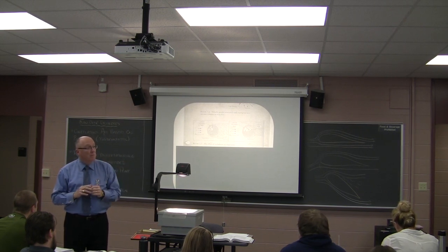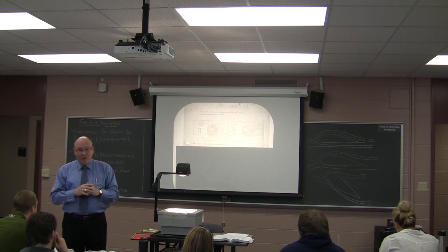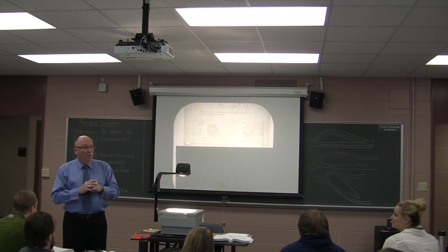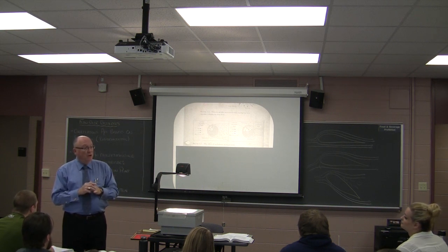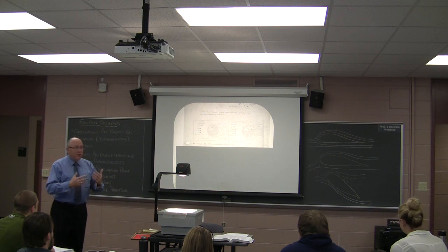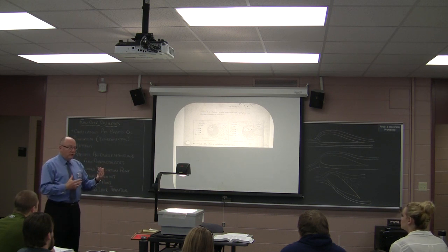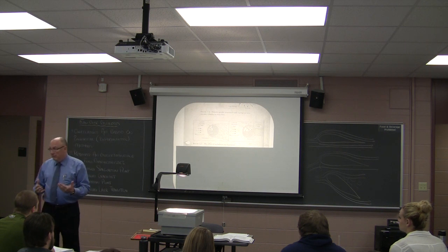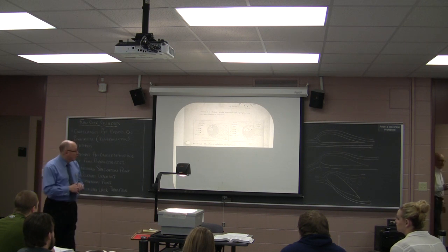So like a golf ball, how they have the holes in it? That's another excellent example of why the surface is roughed, to create a turbulent boundary layer so that the air adheres to it better. You get a better flight. There are also dynamic as well as thermal considerations to all of these things. That's why fluids studies them. Fluids doesn't study it from a thermal perspective, they're studying it from a dynamic perspective. What's happening to the flow.